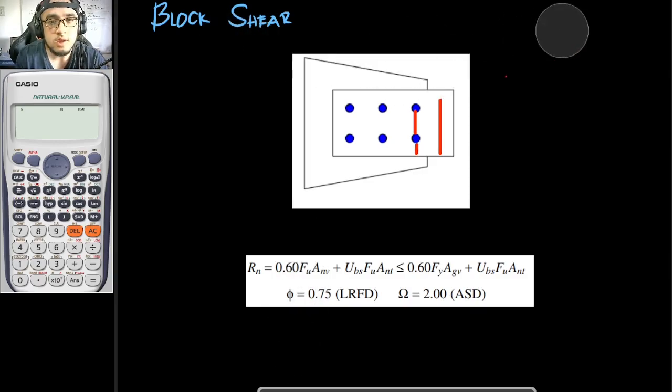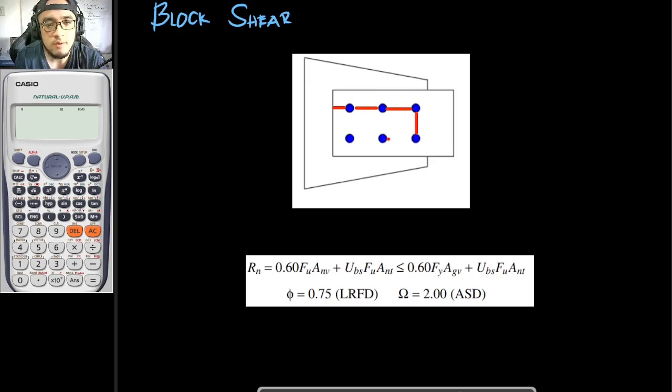And for block shear, let's say that this is your connection, it can fail at this point right here. So this is what you would be calling block shear. This is the manner of failure. We actually have two possibilities here. This part of your plate can be disconnected from this part right here, or it can also fail in this manner. Instead of the one that I have shown to you a while ago, it can also fail in this manner, whereas this shaded area is disconnected from this part right here.